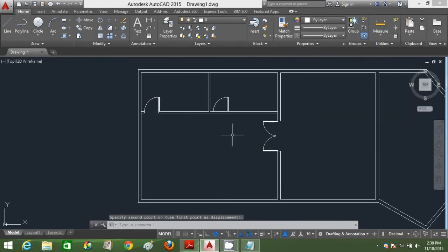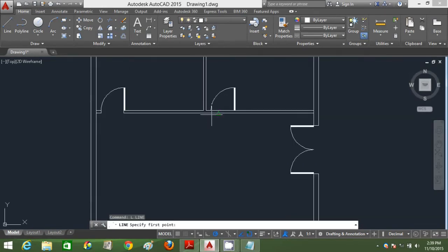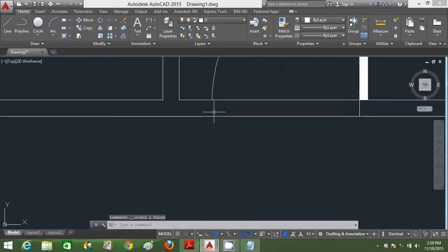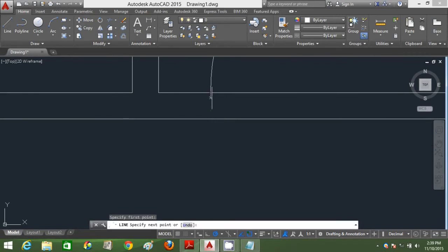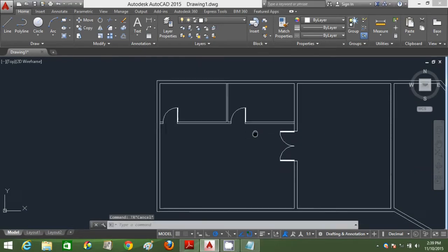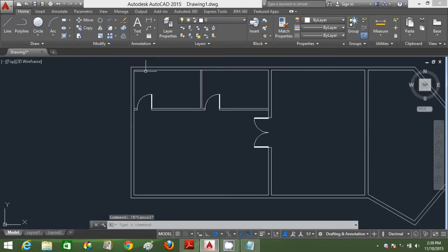So we actually have to set the boundary of the door first. Okay, and trim it out. Delete this one first. Make sure that the line goes straight using your polar tracking. Select the overlap line, trim out the unwanted portions. Alright, so we got that ready.